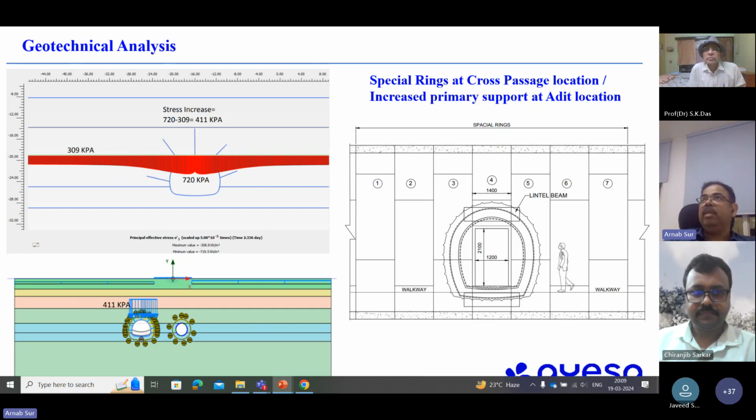And that can be assessed on a case to case basis: how much cover is actually provided, and what the contamination of the water is. Maybe the water is clean, maybe the chloride content is very high, maybe there is something acidic because of a sewer line nearby. So that detailed analysis is to be done. There are codes and ways to find out. But corroded reinforcement should be avoided in the first place. We should not allow any corrosion.